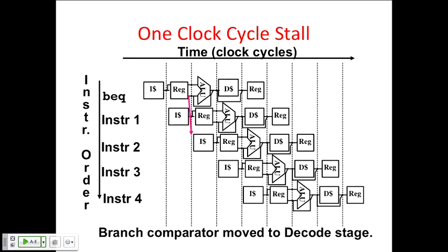So the question was, let's take this example. I do a branch here, and I just keep fetching sequentially. But then here I determine, whoops, that branch was taken, so this instruction was wrong. I fetched sequentially, I should have gone to the target. So the question was, what if this instruction messed up the machine? How do I undo that, because I went down the wrong way?